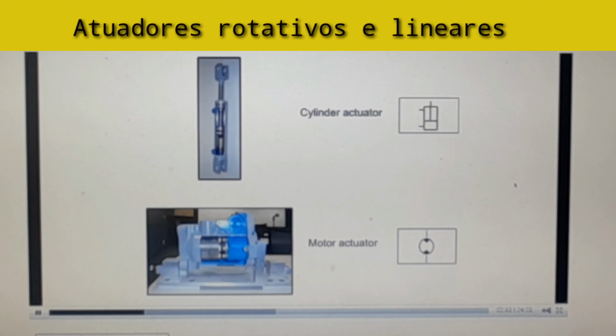There are two common types of actuators that will be covered in this course: a hydraulic cylinder and a hydraulic motor. Cylinder actuators produce linear force, while motor actuators produce rotary motion. Whether the resulting force is linear or rotary, basic hydraulic actuator operation remains the same. Fluid fills a confined space and acts upon an actuator. Inside the actuator, a piston is forced to move. Mechanical components connected to the actuator assembly are also forced to move.